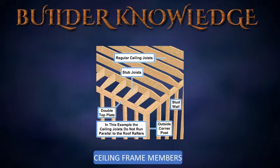They will usually all run in the same direction, but plans sometimes call for different sets of joists to run at right angles to each other. Ceiling joists should run in the same direction as roof rafters when possible. Next is stub joists. Stub joists are short joists running at right angles from a regular joist to an outside wall. They are necessary when rafters and ceiling joists do not run in the same direction.